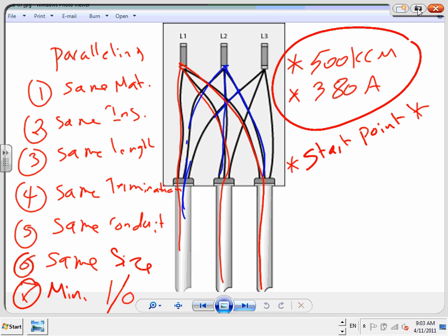If you guys remember when we went to Boston Scientific, they were talking about commissioning the building. And what they do, guys, is they bring those guys who are not electrical inspectors, and they're not electrical contractors. They have every machine that you can imagine. And they say, okay, this transfer switch is supposed to transfer within 3 cycles. Okay, let's go put a load on it. They put a load, literally a load on it, and they push the button and they time it.